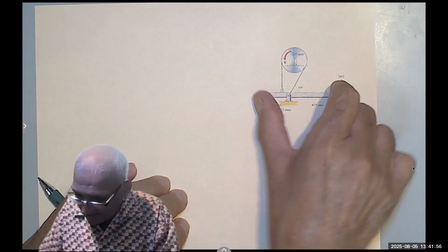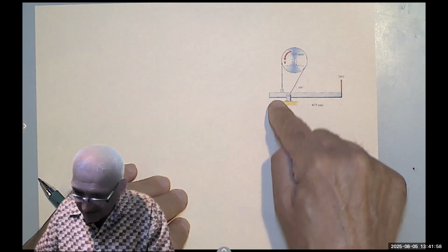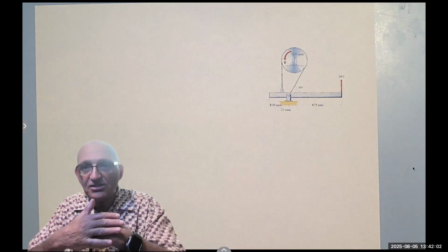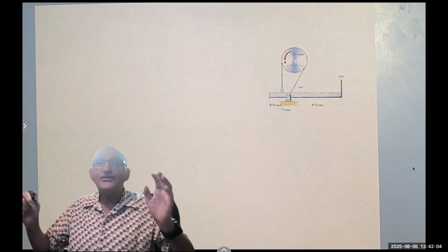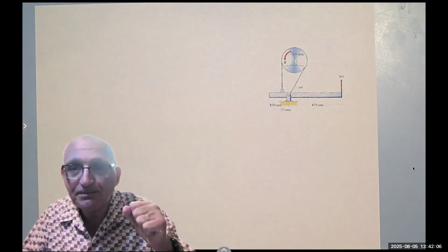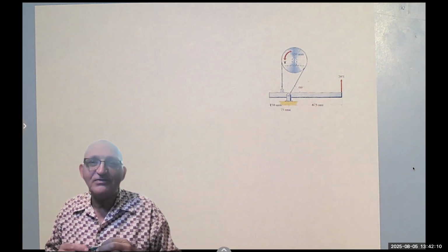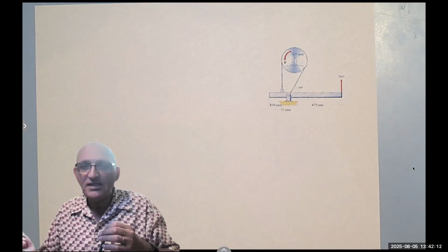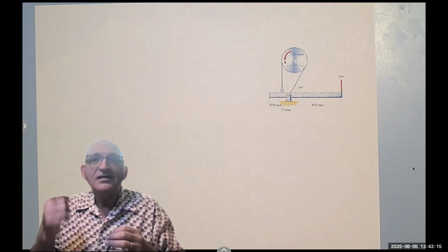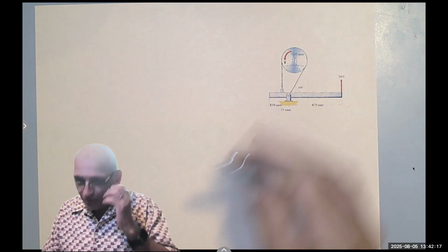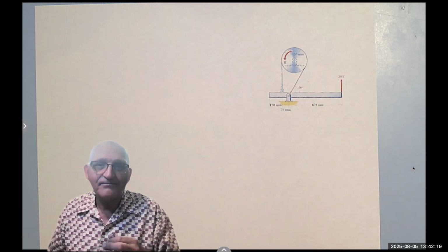When it goes up, it pulls this side and increases the friction until the friction is so high that it stops the band brake. That point would be a point of impending slippage, meaning if you release the force a little bit, the pulley will start rotating again.